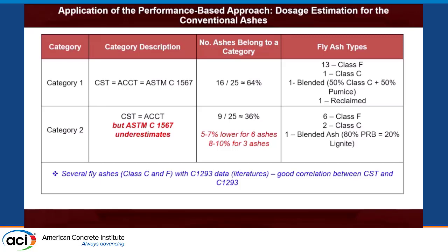Quickly check it. If it is not, then you need a concrete test. Now somebody can say ACCT is a costly test. I'm not recommending ACCT for all. I have a screening. I screen it. You send 20, maybe ACCT 5 I will do, maybe 4. The remaining 15, I will take a decision within 14 days.